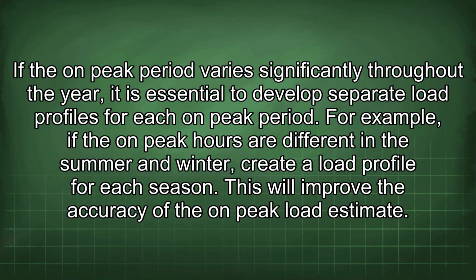If the on-peak period varies significantly throughout the year, it is essential to develop separate load profiles for each on-peak period. For example, if the on-peak hours are different in the summer and winter, create a load profile for each season. This will improve the accuracy of the on-peak load estimate.